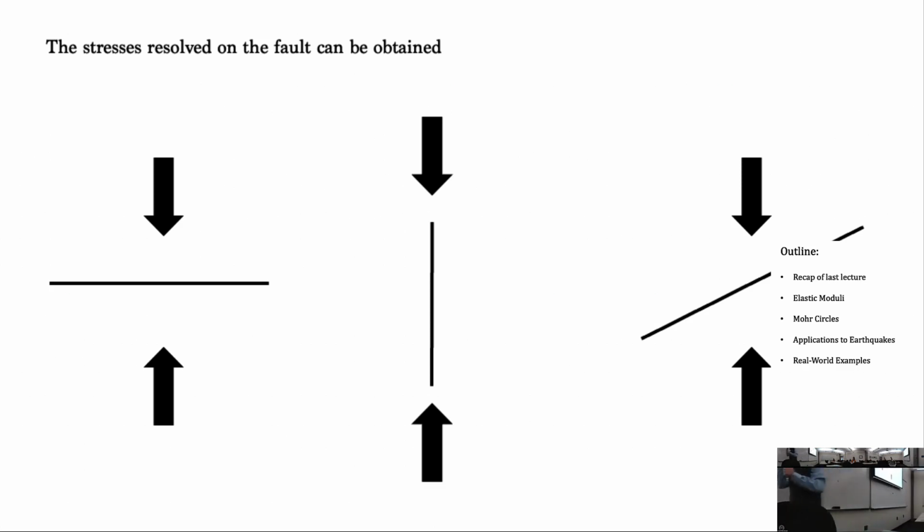Okay, and now I'm going to show a third example. What about this plane? This is the same stress field, just a different orientation of the plane in the stress field. What are the normal stresses and what are the shear stresses? Shear stress is not 0, so shear stress is up here somewhere. And normal is less than the first one. What about relative to this? Bigger than that, exactly. So it plots somewhere over here. I'll just put it right there. Ooh, this is a good marker. And let's call it gamma. Just going in Greek letters.